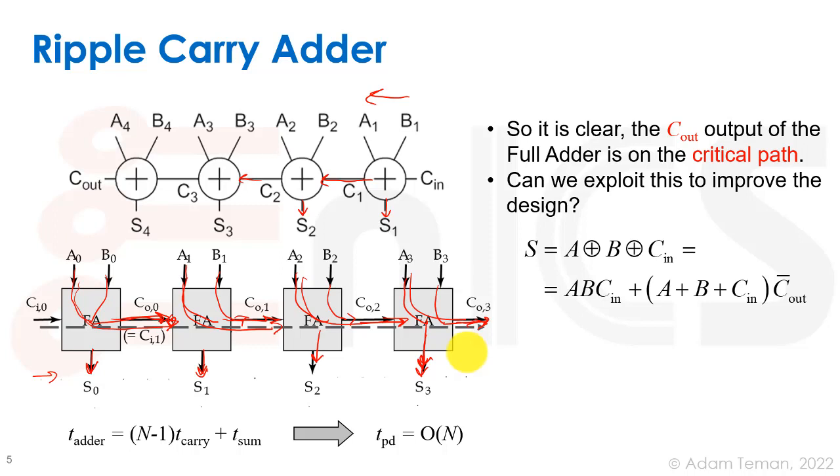We showed in the lecture a cool way of employing logical effort in a very application-specific way, where we know that the carry is the only important critical path and the sum isn't, and therefore we can size everything with the same sizes and fit it in the bit slice.